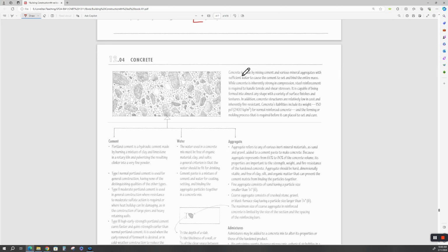They used fly ash. Actually, it's volcanic ash, which is a pozzolan. That means that it absorbs water and gets hard. If you've got an outdoor fire pit and you're burning wood so you can drink your wine or your bourbon with your lover in a nice romantic setting, and you don't cover it and it rains, and you go to scoop out the ash to clean it up, you'll notice that over a period of time the ash is hard because it's absorbing that water.